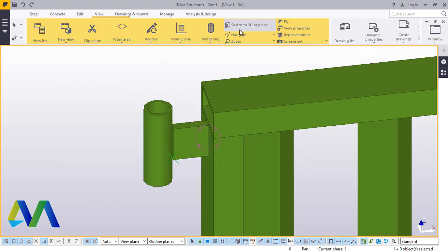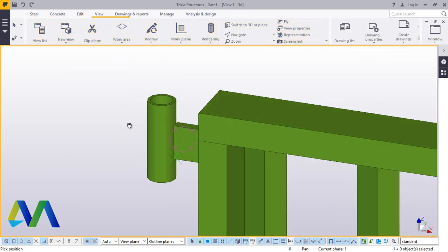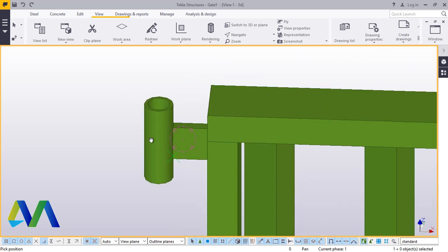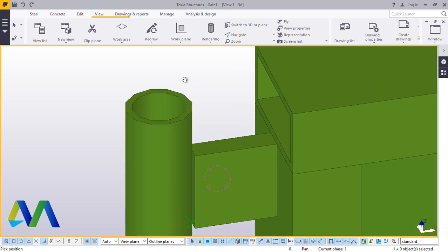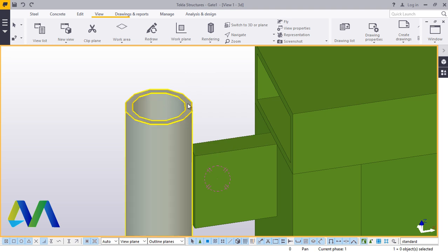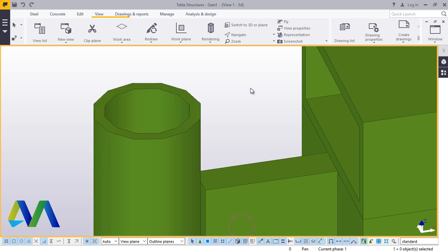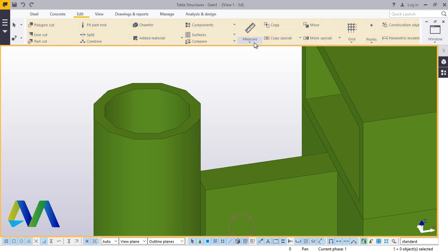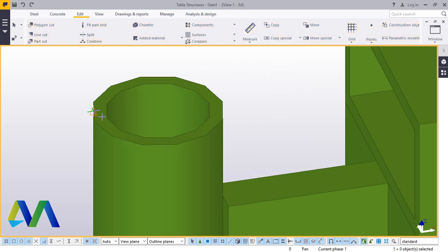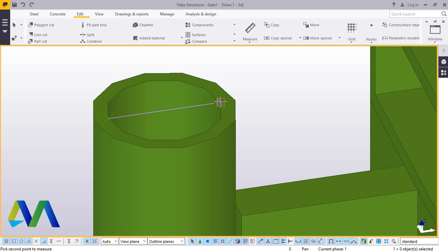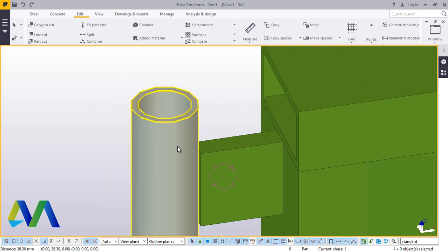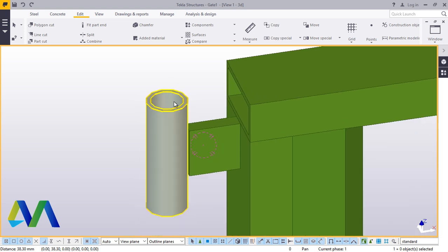Now you can come to navigate, rotate with mouse like that. Take into account that the internal diameter is 48mm. You can confirm that. If not correct, we will modify. Click that and click that. It's 38. So we need a rod that is less than 38.